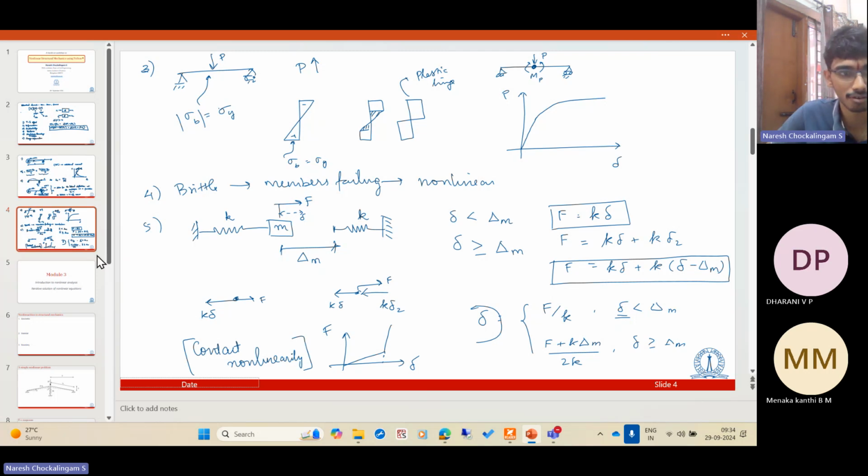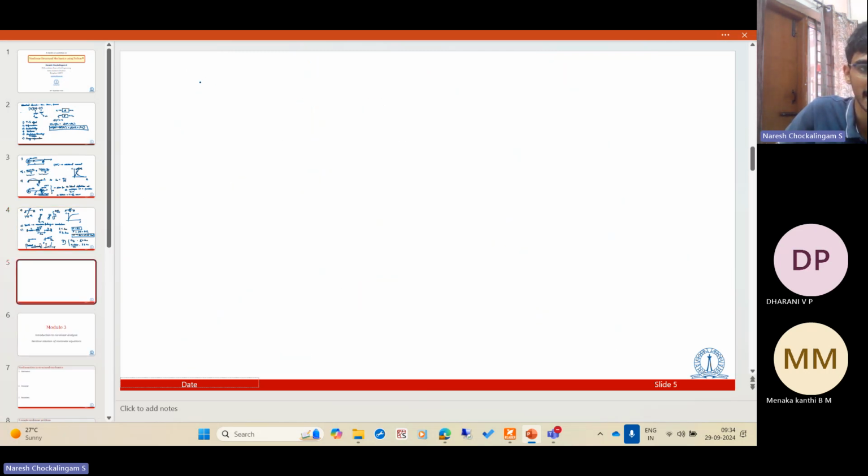And in 2-dimensional or 3-dimensional bodies, you can have things like a balloon. You can press it against, say, the wall, right? You can press it between two walls, and you actually don't know which part of the balloon will be in contact, right? So it can have a contact area A. The balloon has some internal pressure P. And we actually don't know this area, right? So the condition is over this area, the balloon is flat, and in the rest of the places you have some pressure P. So we know neither the force that is acting on this area nor the area itself, A. Therefore, this is a contact problem.